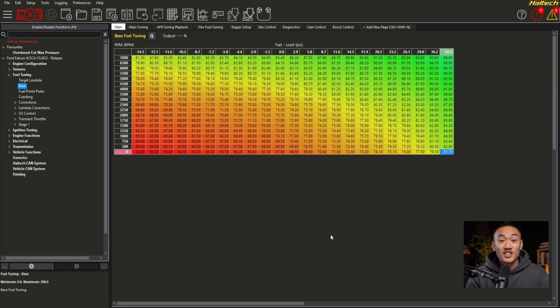In reality, engines are not perfect air pumps. Restrictions in the intake, cylinder head, valves, camshaft timing, exhaust system, and even the throttle mean the engine never fills the cylinder completely. That difference between how much air the engine could hold and how much air it actually traps is what we call volumetric efficiency. So VE is simply a measure of how efficiently the engine pumps air from the intake to the exhaust.